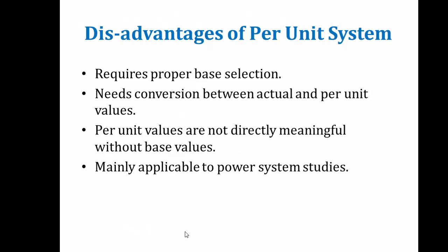Similarly, we will see the disadvantages of the per unit system. Coming to the disadvantages, first we have to select the proper base. If you do not select the proper base, then it leads to error. Then we have to go for the voltage conversion for different components, so that needs conversion between actual values and per unit values.